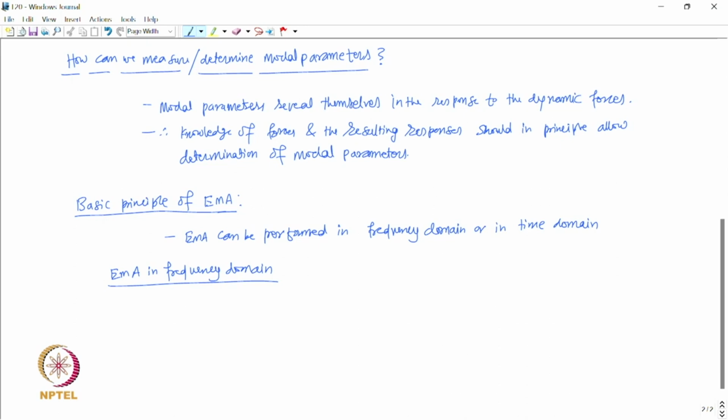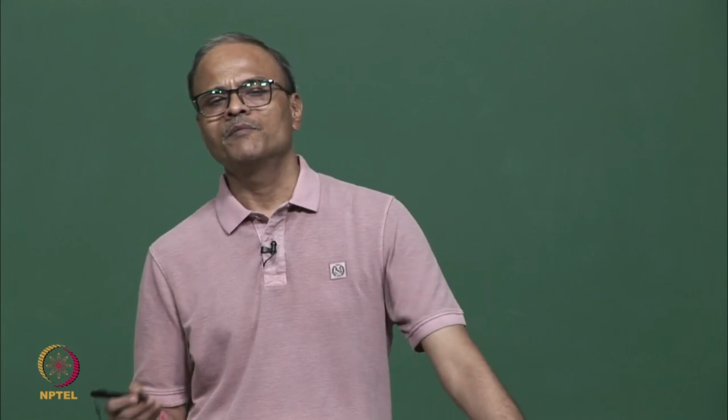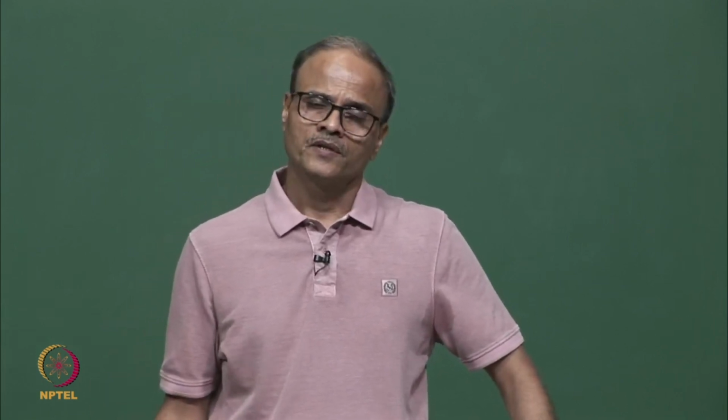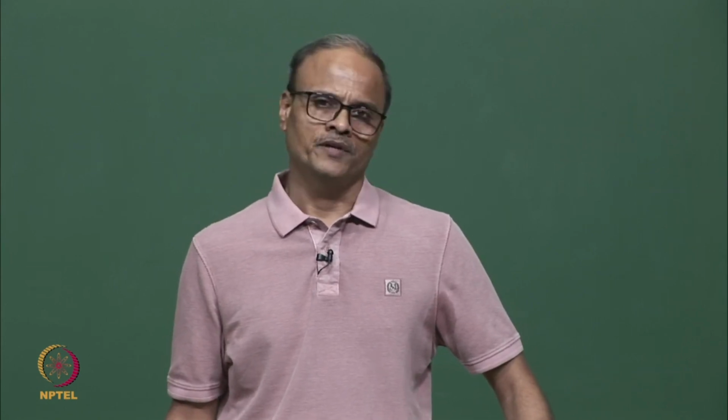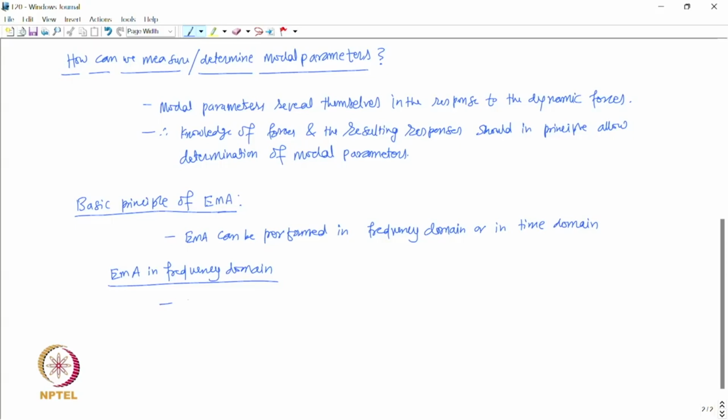So, in the frequency domain, the dynamic forces and the responses they cause are related by the frequency response function matrix. Okay. And the frequency response function matrix essentially constitutes the response model of the system in the frequency domain. So, the FRF matrix relates dynamic forces and responses in the frequency domain.